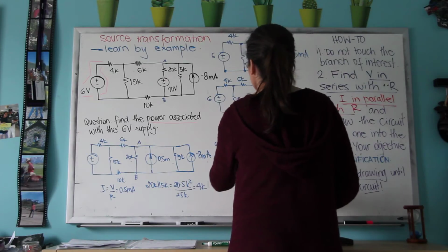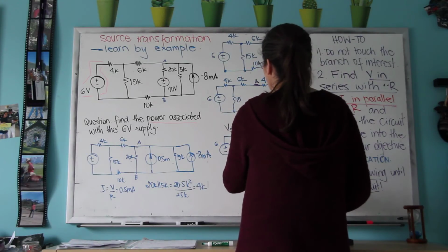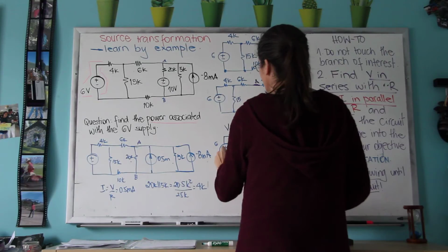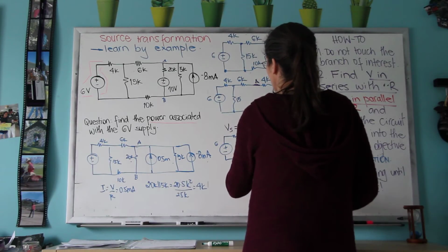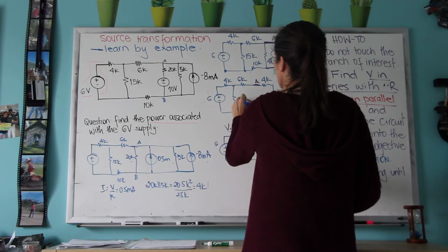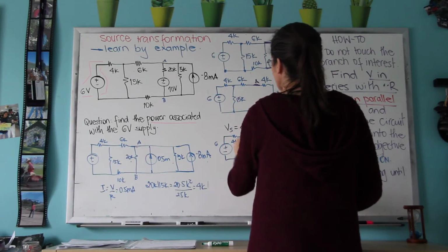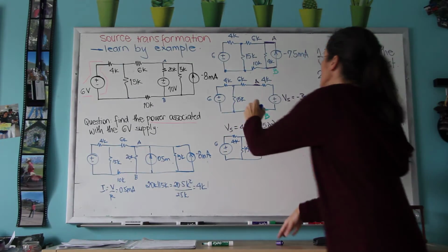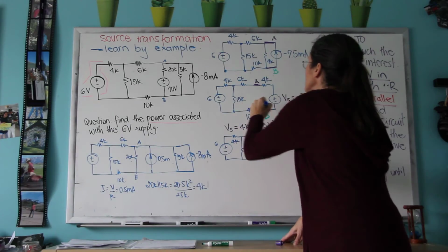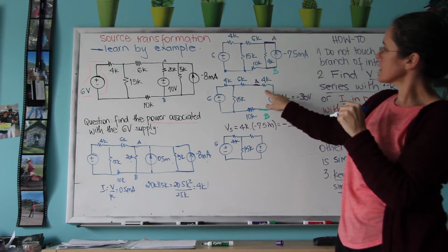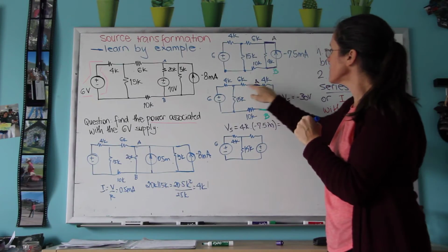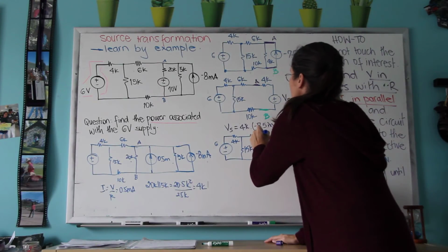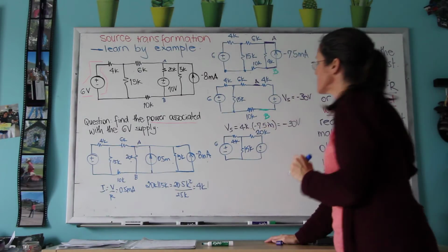6, 4, and I think this was one question in the class. How is it that I can just do this? The answer is this is a 10K resistor. It is in series with the 4K and the 6K. It's also in series with the voltage supply. But resistors in series I can add up. And this is therefore a 20K resistor.